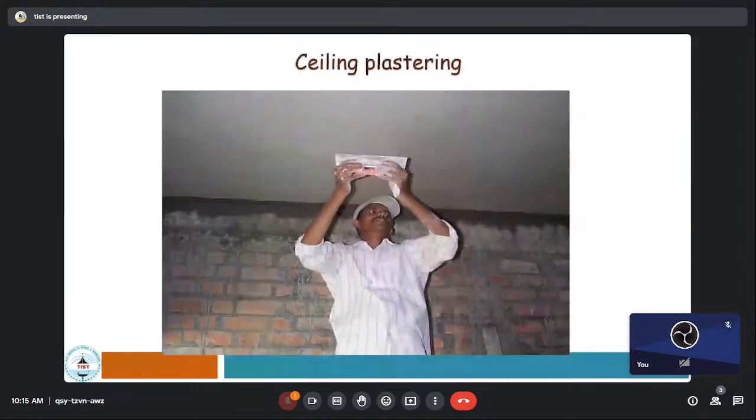And you go for ceiling plastering. Persons, while doing plastering, will include a high amount of thickness also. So, n number of places where the plastering thickness is more than 1 centimeter. Plastering thickness has no value. Plastering is measured in square meter.